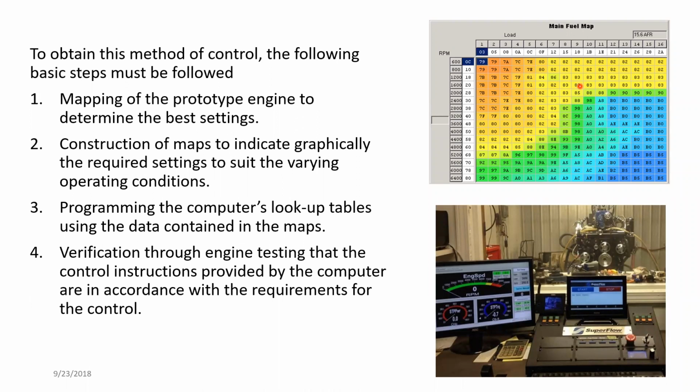Once you have filled in all of these values, it develops a sort of surface, something like a map, right? Finding out these values and storing them into the engine computer module, or engine control unit, is known as engine mapping, right? So whenever a new engine is developed, all of these things have to be mapped.